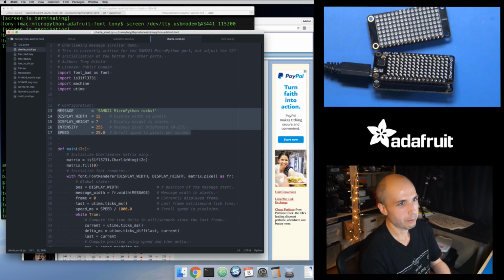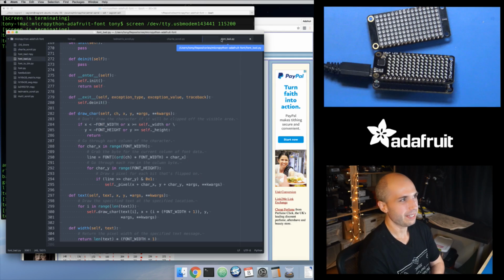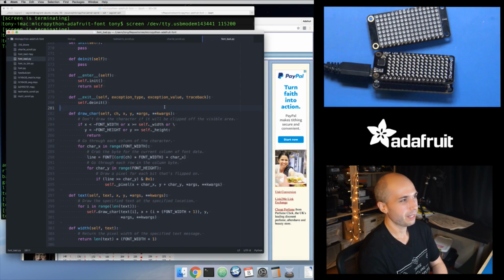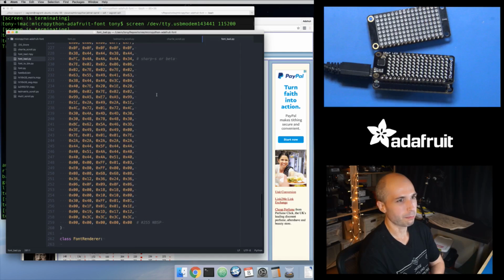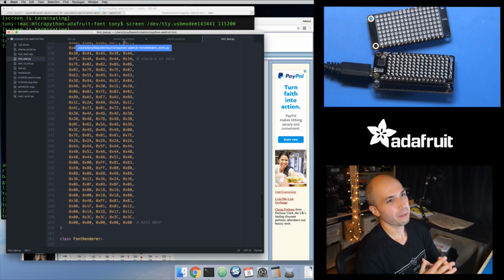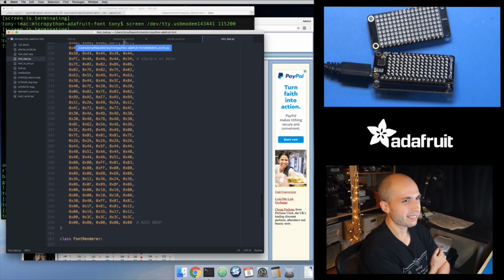I tried the .mpy file module. That didn't really help, because that helped me to get the file onto the board. It's a smaller size, but importing it, now everything explodes. So I stepped back and thought of an interesting way to solve this. Earlier today, talking to Scott, we had a good idea. One way that I solved this was I can freeze this module into the MicroPython firmware. Even that takes a lot of memory.